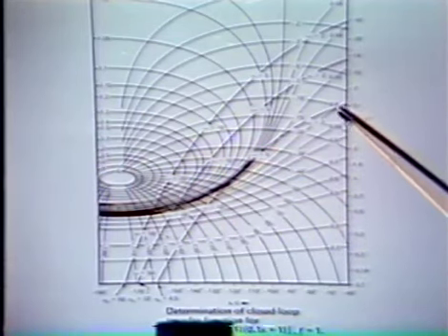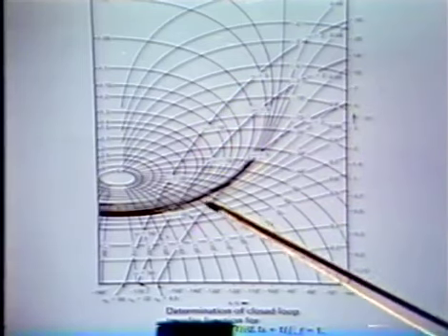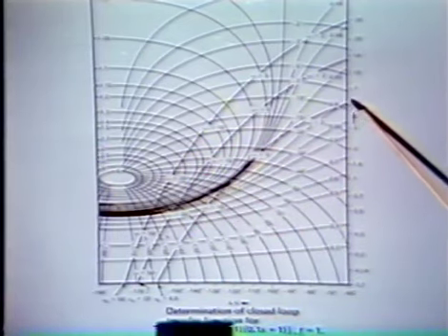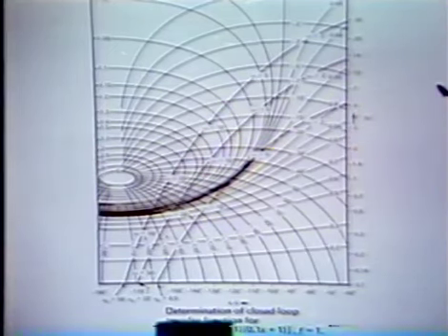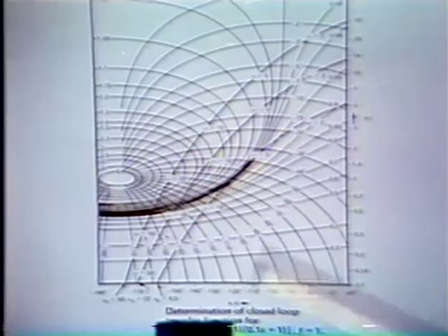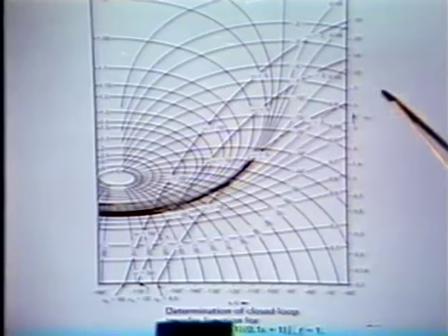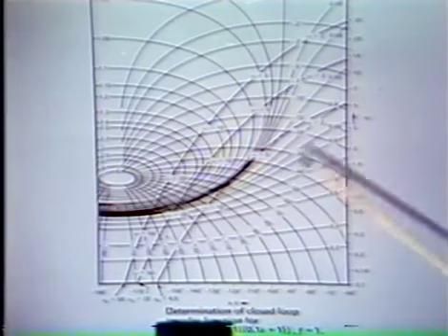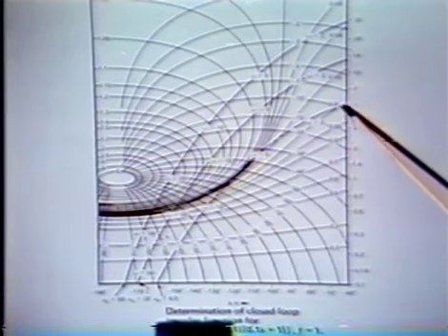For example, if we look at the AF product that corresponds to an A0 of 8.5, we find out that at sufficiently low frequencies, back near omega equals 0, this curve eventually levels out at 0 degrees and a closed loop magnitude of about 0.9. We can get that either by analytic manipulations or look at the complete chart. We find out that the low frequency closed loop magnitude for this system with A0 equal to 8.5 would be about 0.9.